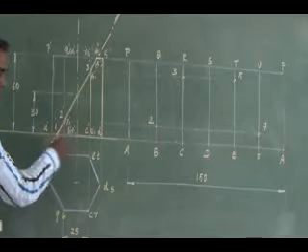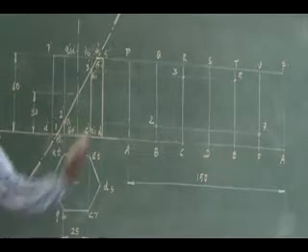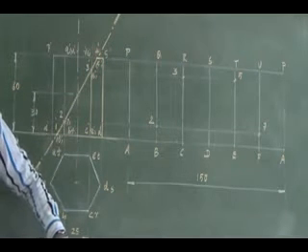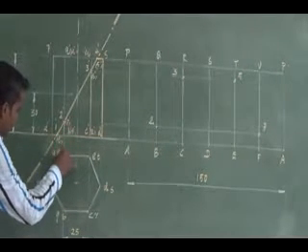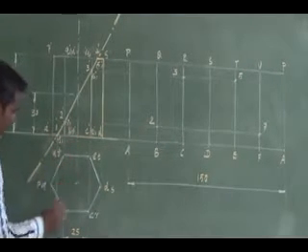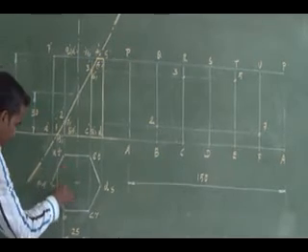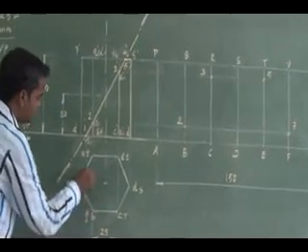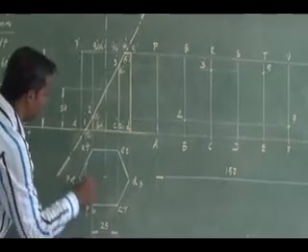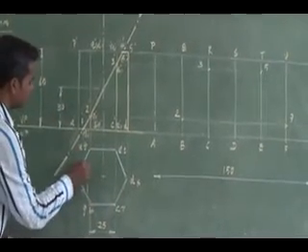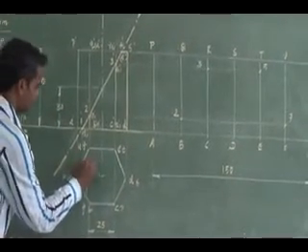So this cutting point, which falls on the base, should be projected to the top view to get the exact location of the cutting points on the base. Right? So I can project these base cutting points to the top view. Wherever it cuts along A and B, that is my cutting point 1. Along F and A, that is my cutting point 8.